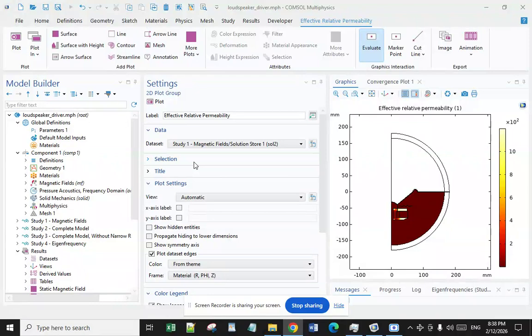And what are the applications? Electromagnetic acoustic transducers have been used in a broad range of applications and have the potential to be used in many others. A brief and incomplete list is as follows. The first one is thickness measurement for various applications. The second one is flaw detection in steel products. The third application can be plate lamination defect inspection. The fourth one is bonded structure lamination detection.